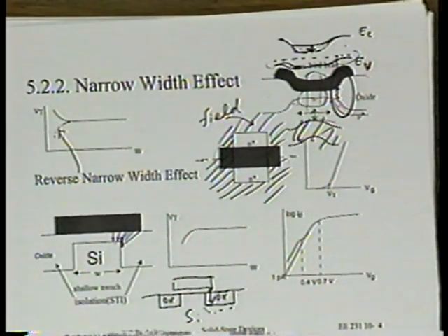Question? So does that mean that the current starts flowing at the edges of the transistor? Absolutely right. It will first start to flow there. Truly, it actually starts to invert first. And in fact, usually this is only seen during development. By the time the technology is released to the circuit designer to design circuits, you don't see it.